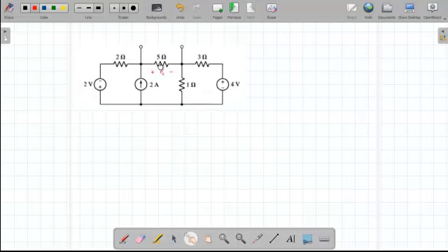First of all, of course, we don't have any dependent or independent sources. So our Thevenin calculation, I think, is straightforward. Just this resistor, these two become in parallel, then become in series with 2, then become in parallel with 5. So we can say our Thevenin,